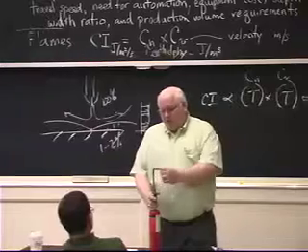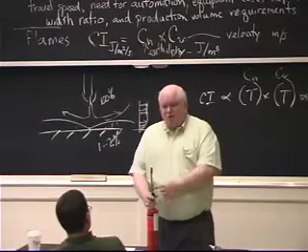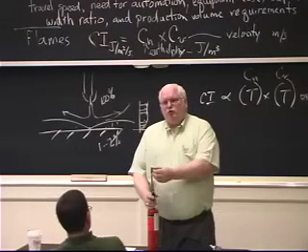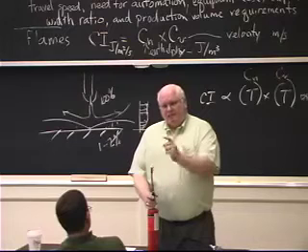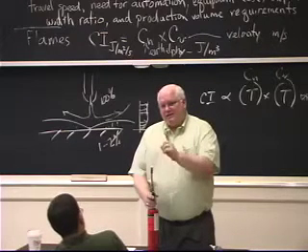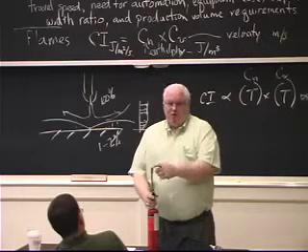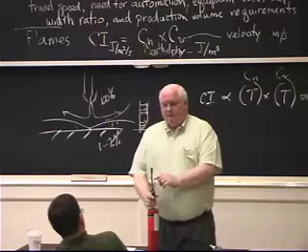Right now, the velocity of this coming out is basically proportional to the pressure of the gas coming through that orifice and how much air it's dragging in with it. So it's the cold velocity of the gas that's coming out. And that velocity has to exceed the combustion velocity of this fuel, which is characteristic of the fuel in the oxidizing medium, air in this case. Otherwise the fuel would go right back down.